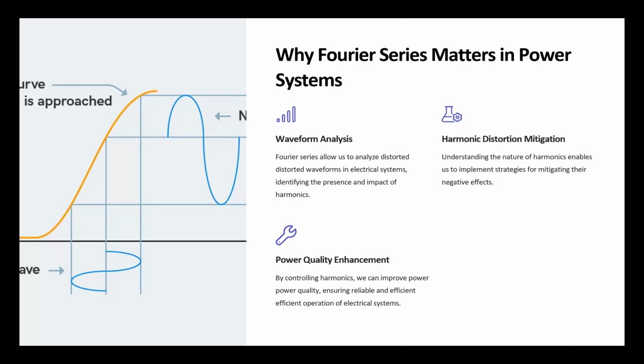Because as we talked about when we talked about AC circuit analysis, one frequency at a time. We cannot combine two frequencies in one analysis. So if we want to see what's going to happen to that motor, we have to first do the analysis based on 60 hertz, find the result, which is the normal operation, then go back, cancel out the 60 hertz, add the 180, and see what's going to happen. One frequency at a time.